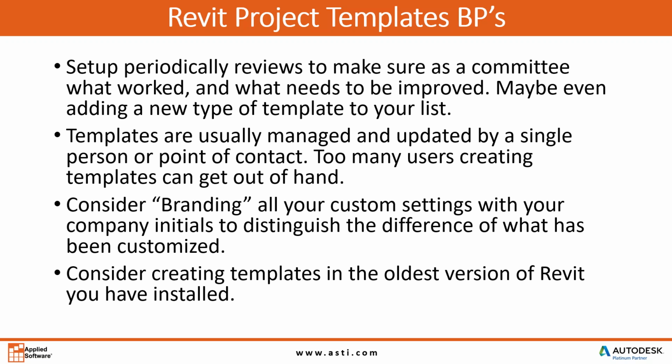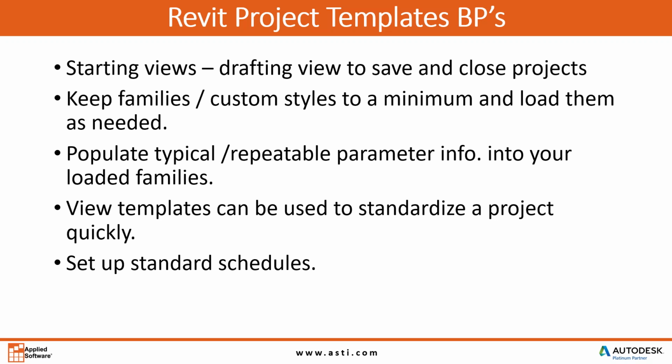Also, consider creating templates in the oldest version possible. I have 2016, I think, is the oldest on my computer. So anything that I do in mine, I do in 2016. And with the new features in the newer versions, you might want to manage a template for each year. Create starting views. Again, they could really help open and close projects. Keep families to a minimum and load them as needed.